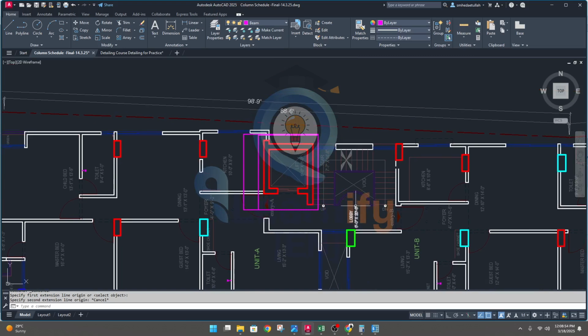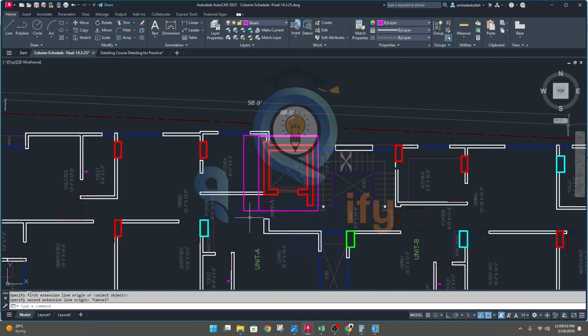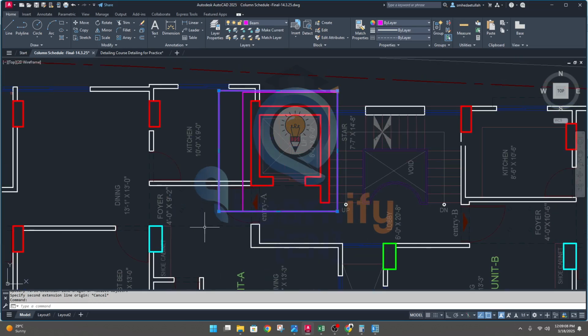So to do it, let's say I will consider 2 feet. What is the value actually here? 2 feet and 4 inch. So I'll move this 1 feet 1 inch. Okay, click move, click here reference point, and on that side must open this option, ortho mode. Then on that side total 13 inch, enter, done. I will delete this one.